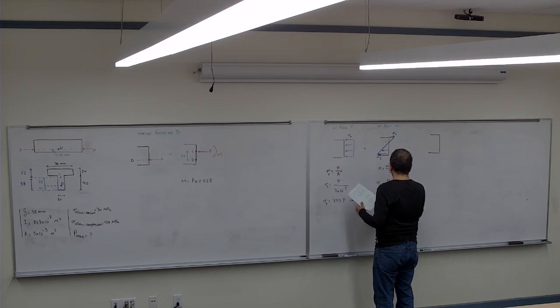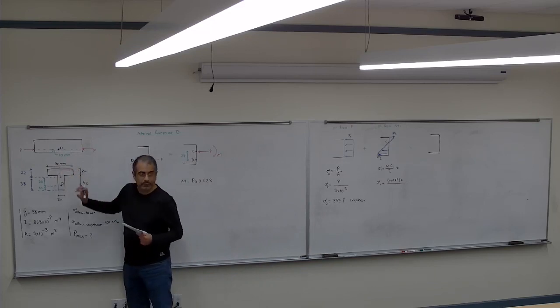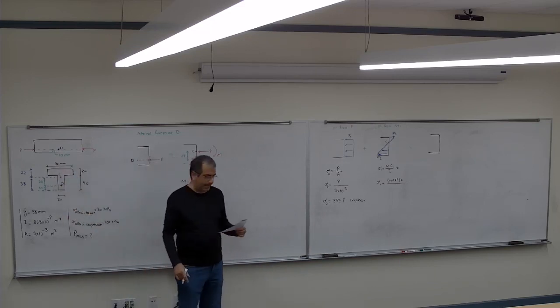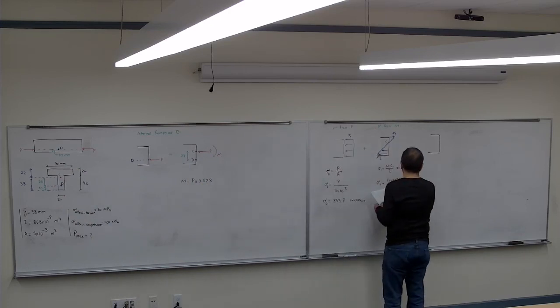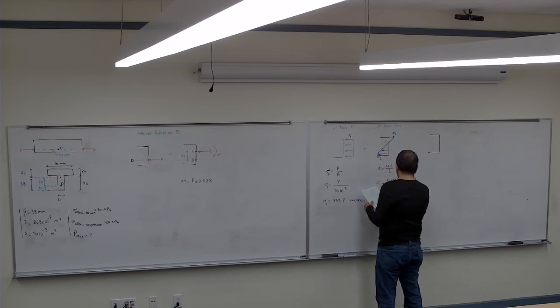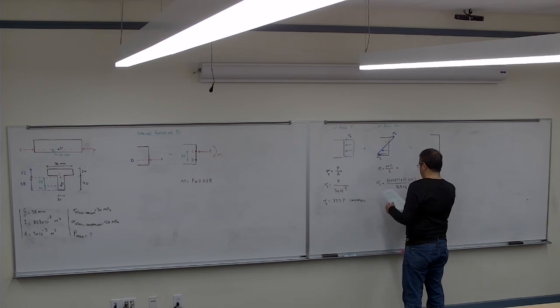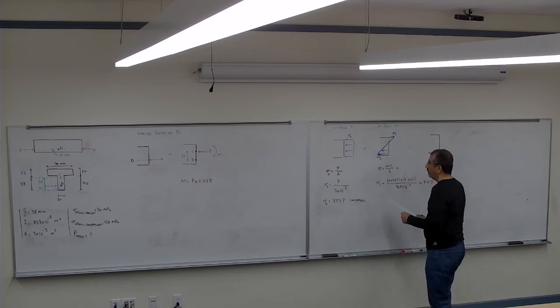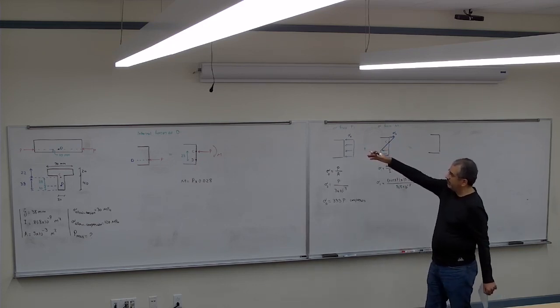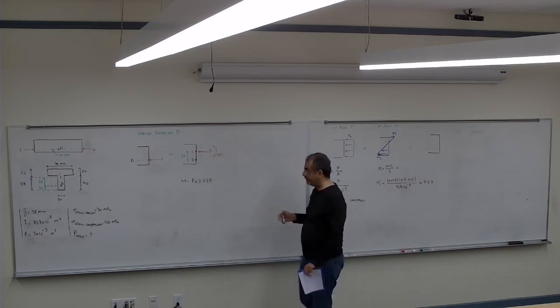which would be the M that we calculated, 1028P, times the C1 at the top, which is 22 millimeter from the centroid to the top. So it's going to be times 0.022 divided by I, which is 868 times 10 to the negative 9, which gives us 710P. And on the top is tension, since this is the M.